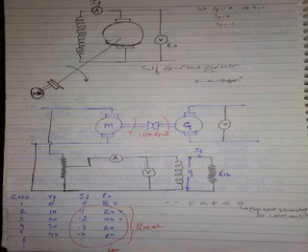So when IF is 0, the OCC starts from some value, the residual voltage, 6 or 8 volts. After that, it will be linear, and after that slowly it will get saturated. This is actually known as the knee point. OCC represents the magnetization characteristic.